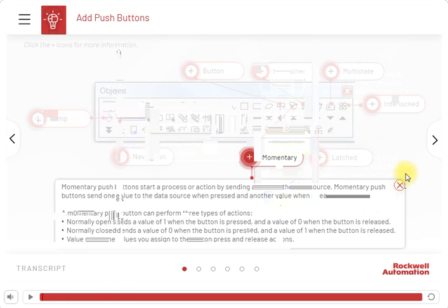Indicator objects show the status of a process or operation by showing colors, captions, images, or options to indicate different states. You specify the state values of the multi-state indicator, and then at runtime, the object displays the state whose value matches the indicator tag value at the data source.